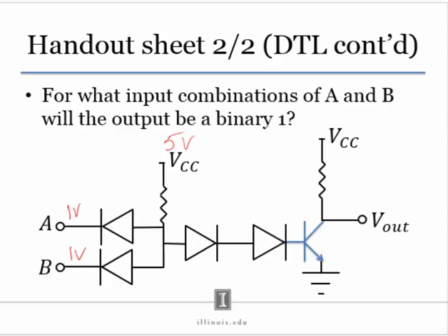but now we're going to have the base voltage here of 1.7, right? Because it goes up now by 0.7 volts with respect to 1 volt. All right, so this is now base is 1.7 volts.